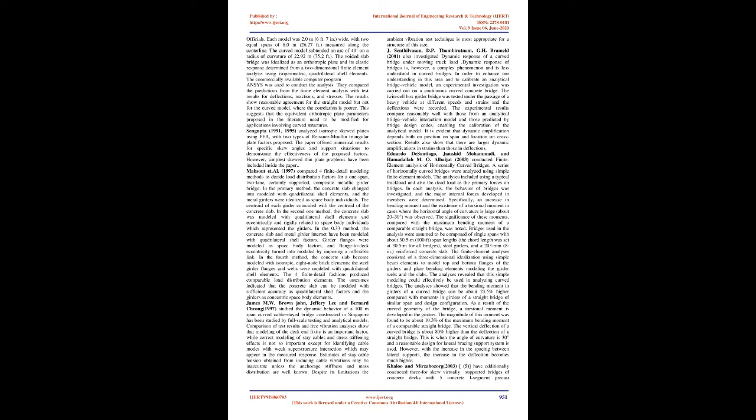Each model was 2.0 m, 6 feet 7 inches, wide, with 2 equal spans of 8.0 m, 26.27 feet, measured along the center line. The curved model subtended an arc of 40 degrees on a radius of curvature of 22.92 m, 75.2 feet. The voided slab bridge was idealized as an orthotropic plate and its elastic response determined from a two-dimensional finite element analysis using isoparametric, quadrilateral shell elements. The commercially available computer program ANSYS was used to conduct the analysis.